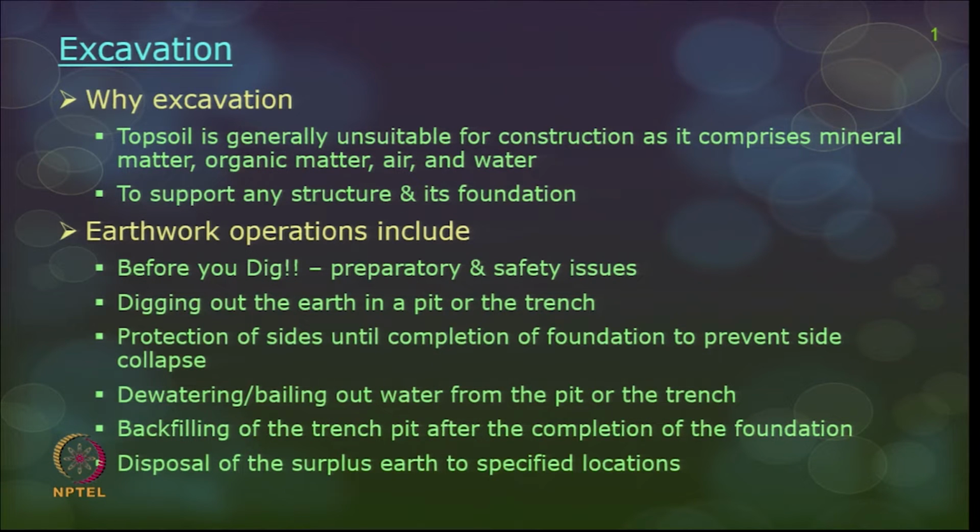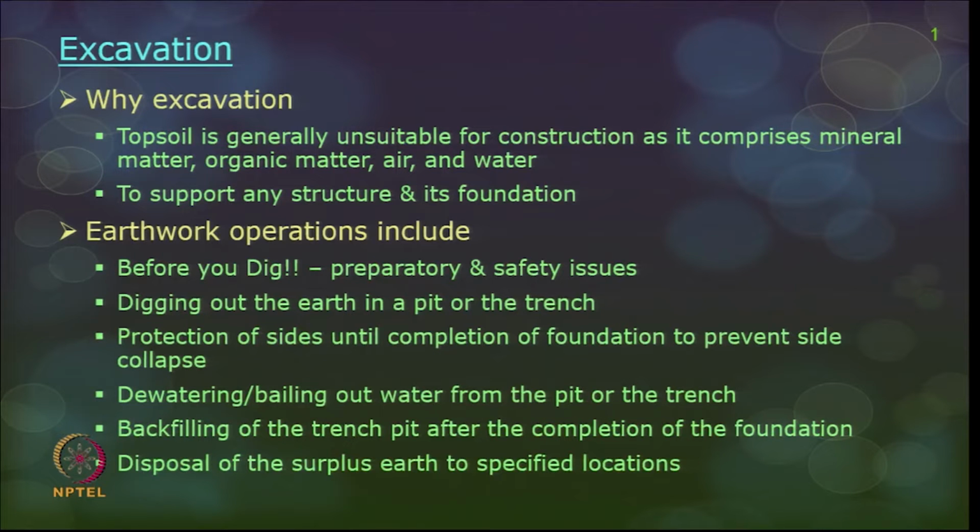So, when you say earthwork, it is not just one single operation. Okay. There are so many steps in the earthwork operation itself. If you start looking, there are some preparatory issues before you dig, and then you have to think of how you dig. So, the choice of equipment and combination and so on. Then digging out, how exactly you have to dig along with protection of sides and the shores until the foundation is completed, preventing side collapse.